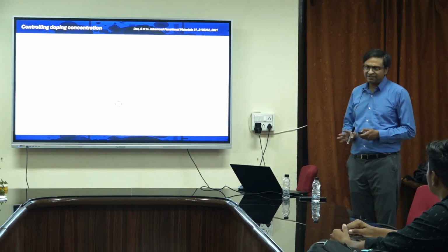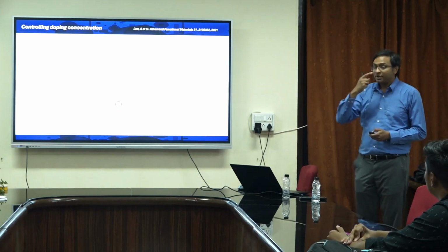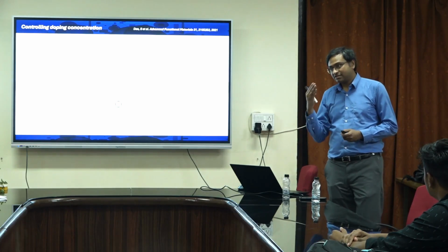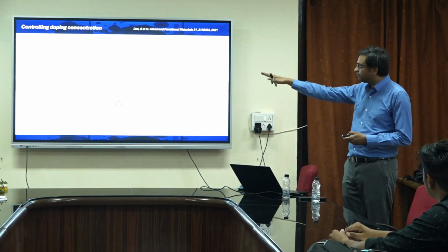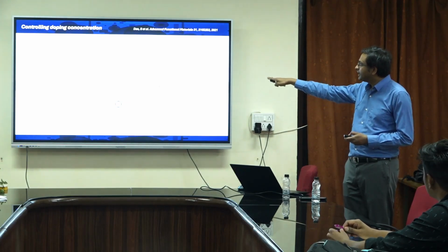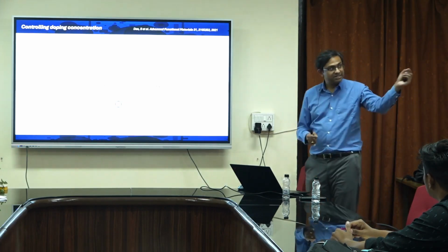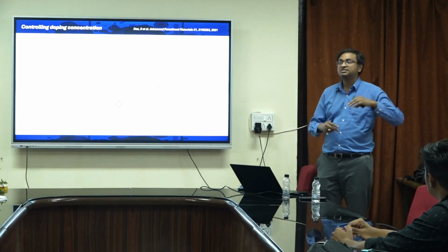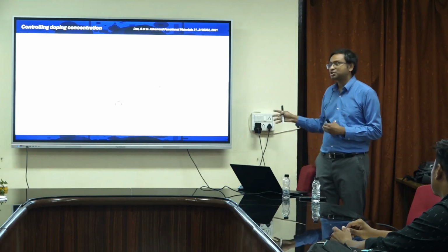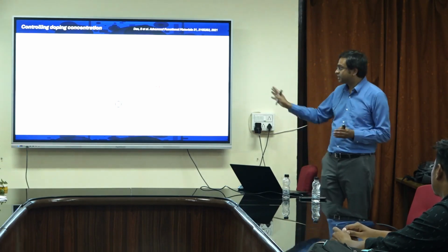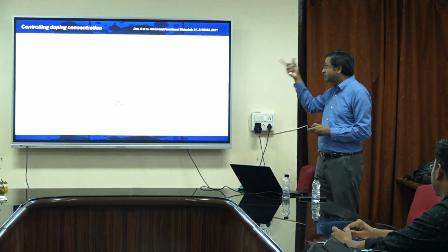Now there are also other works that we have done. They are not as exciting, but this is more recent work. At the end of the day, it is not just the doping, but also controlling the doping percentage, right? So when you're doing large area, we have started looking into whether we can create different doping percentages. That will give me a little bit more control over the channel, because otherwise it is arbitrary doping. And when I make a device for circuit applications, I need the right threshold voltage. I cannot work with any threshold voltage. So we have started looking into different doping percentages and how I can tune the properties by that.